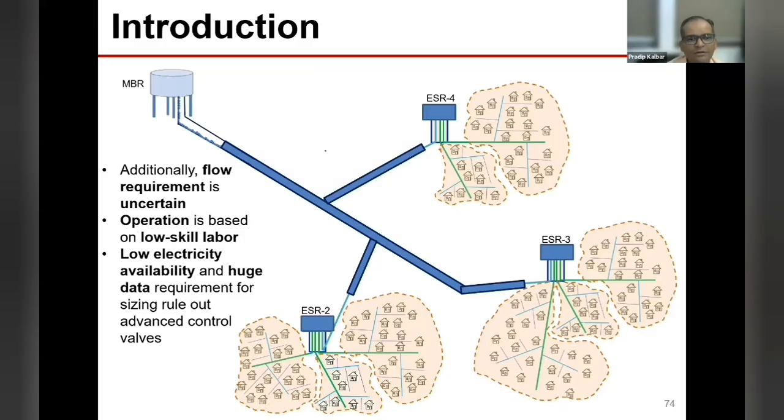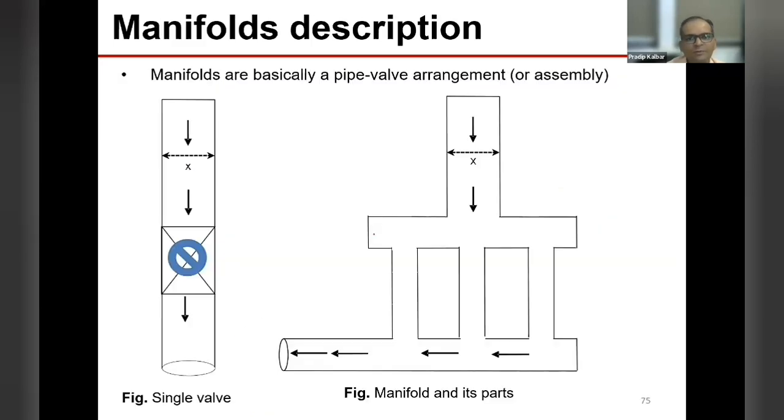What is happening in most of the distribution systems is these large diameter pipelines, when the withdrawal is too high and/or there is a steep slope, run partially full, and then there will be air entrapment because of sagging pipes and many issues. So unless we address these issues, no amount of energy or pumping will help us. So this may be open channel flow, create air entrapment, and part of the system will be pressurized.